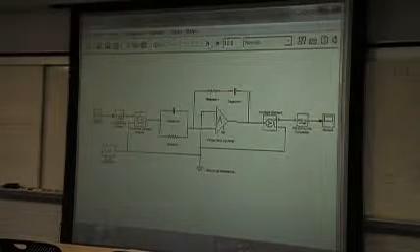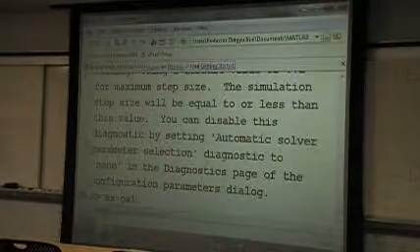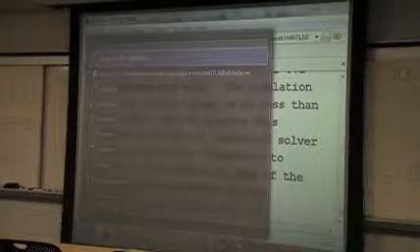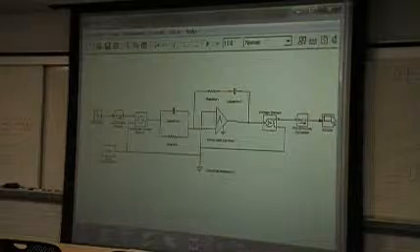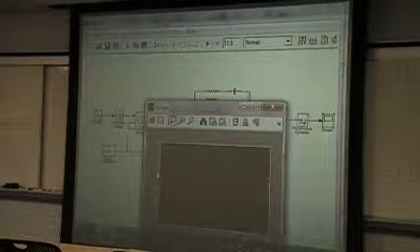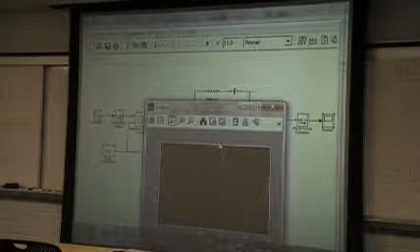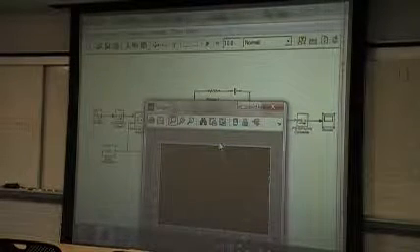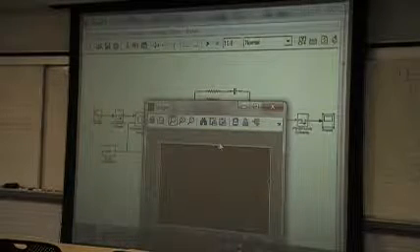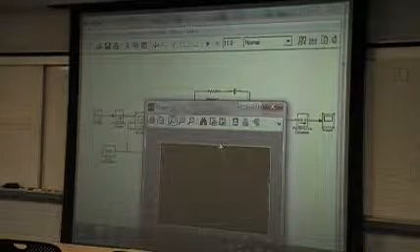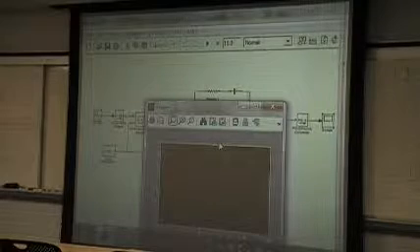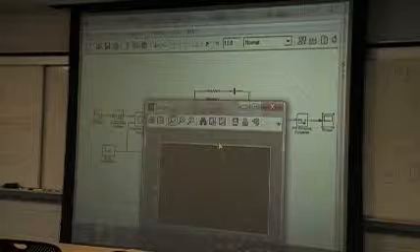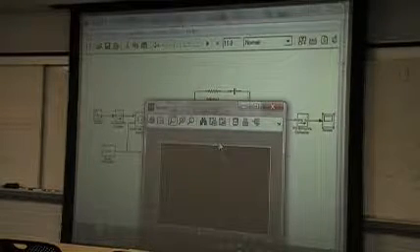And if you reduce the size of the input signal, the amplitude reduced to 0.1, then double-click this one again, and it can be seen that it is now linear. It is a linear system for small inputs. However, for large inputs, actually the input is not quite large, 0.3 times sine t. So for a signal like this, the output may not be a sine signal, because the operational amplifier here is non-linear. It reaches the saturation area, so it is no longer linear.